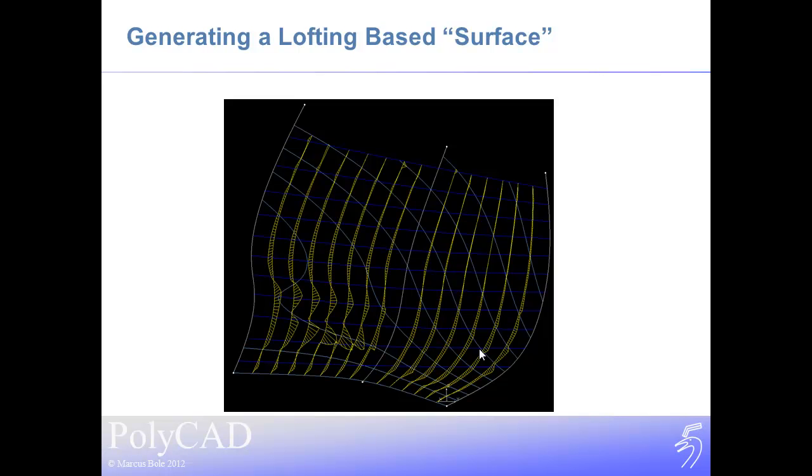And we can see, for example, here that the surface, or the implied surface that we're creating, might not be as fair in particular areas. So perhaps the curve compatibility isn't that particularly good, even though it kind of looks fair. We could also, in this case, change the process. So, for example, say we fitted the waterlines, sections, and then buttocks, and we have a much fairer representation of what's going on. But we start to see some of the limitations of an automated method, that it doesn't necessarily pick up all the information that we want.